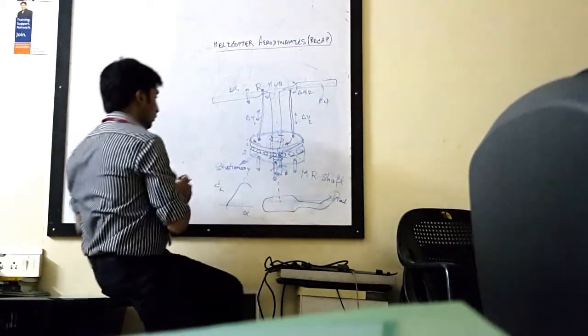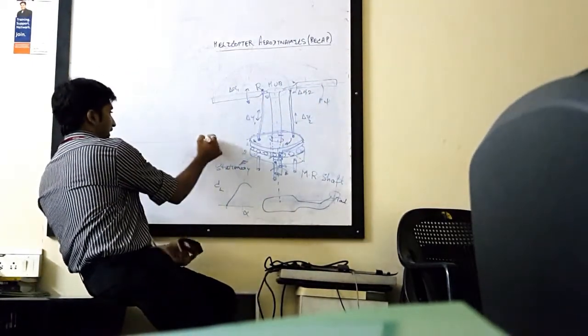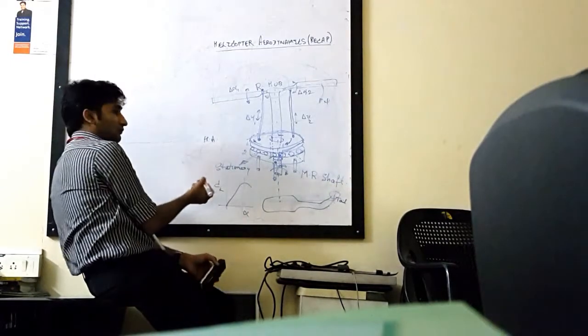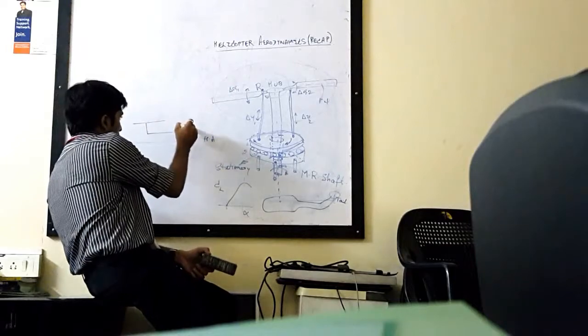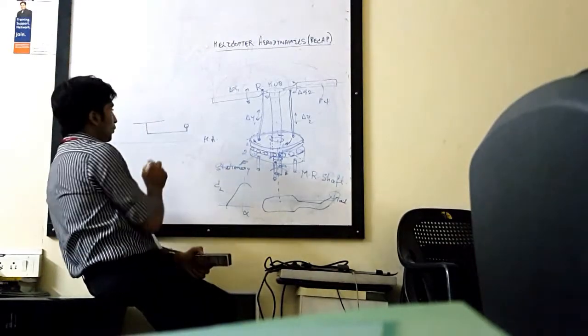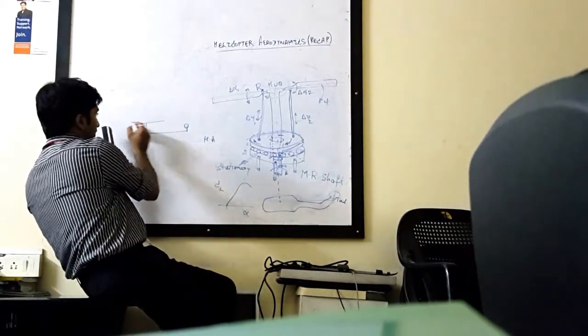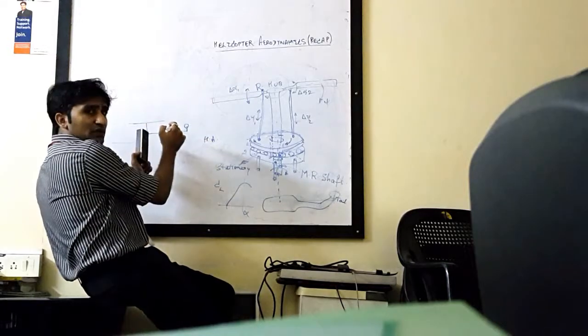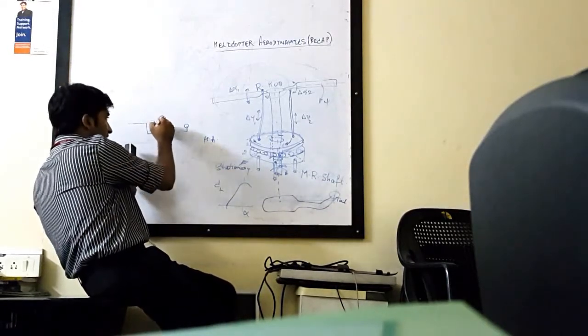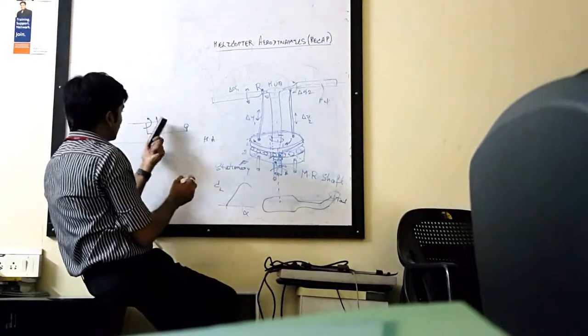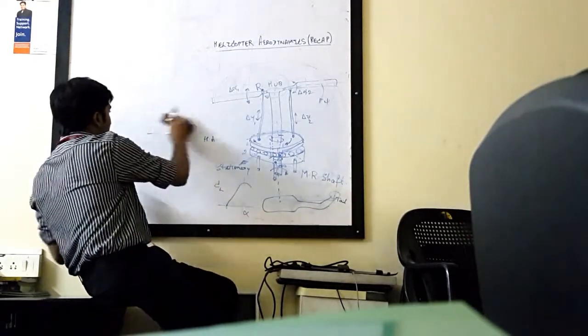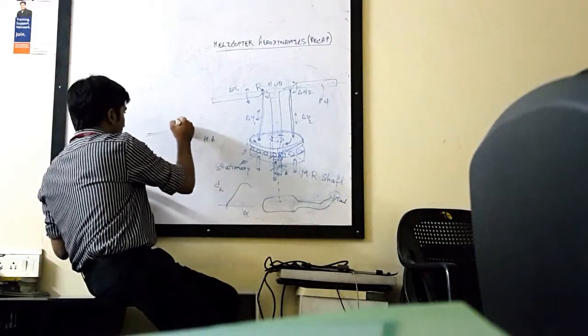Once you pitch down, what happens is, suppose if this is your horizontal axis, okay, when this is your horizontal axis and this is your helicopter. Now once the lift on this side of the rotors increases, okay, so this is going to produce a moment. Alright, this is going to produce a moment because of which the helicopter will assume a position like this.